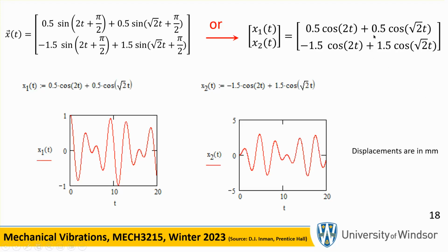Now we can plot these. The location of mass 1 as a function of time is here. The location of mass 2 as a function of time is here. Notice that these are all periodic. These are all sinusoidal, but involve both frequencies. In general, if the initial conditions are arbitrary, you will have both frequencies popping up in your solution for the physical variable.